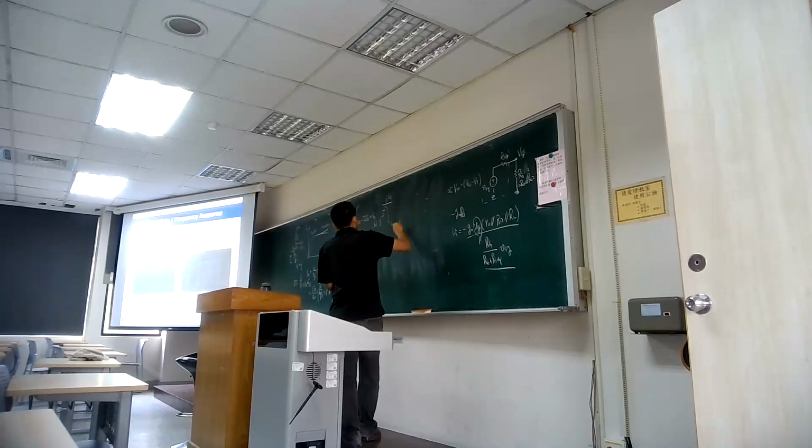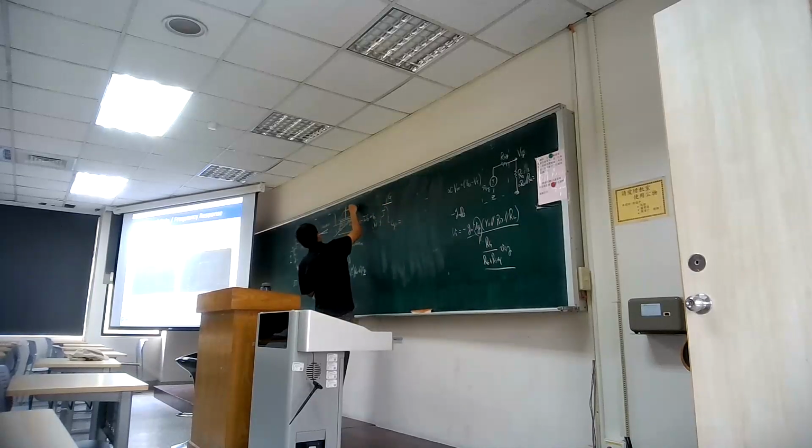So you can think that the capacitance will be something like, what is the area here? The area is, maybe I draw it with a three-dimensional space. Okay, so here is the unit capacitance of oxide. And here we have a plate. So the capacitance is the area divided by L, but the L is denoted by here. So I use different wording, maybe divided by T. So C oxide is epsilon oxide over T oxide. Okay, so it is the thickness of the oxide layer.